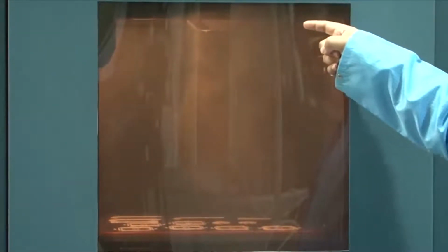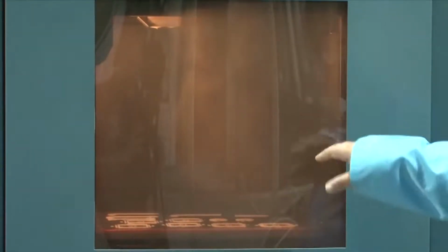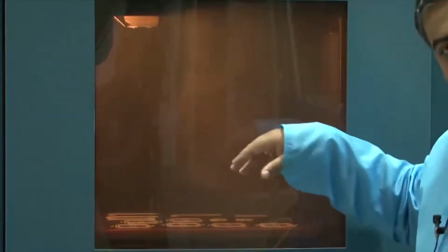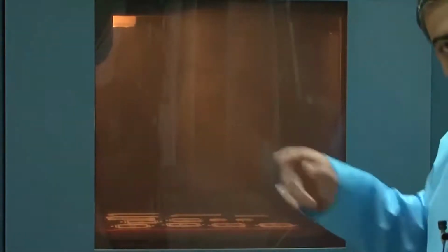So it is still homing the XY gantry and the Z stage, okay, so this process will take a little more time. You can also see right on the top here is the dispensing nozzle, which has come up and is now trying to position in the XY direction, once the Z is defined by the workpiece. Then it will be all about the way the nozzle dispenses, and the correct tool path would be mapped as per the CAD slice, which would come few hundred microns by few hundred microns as you construct the final part.